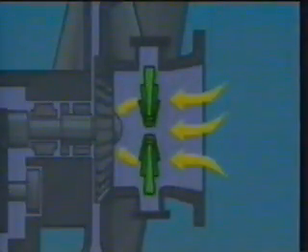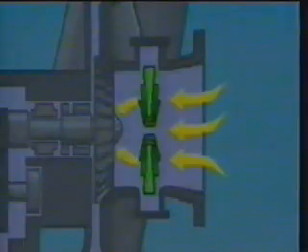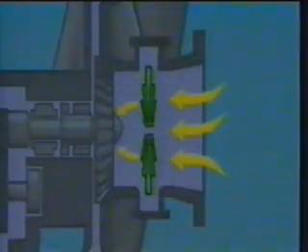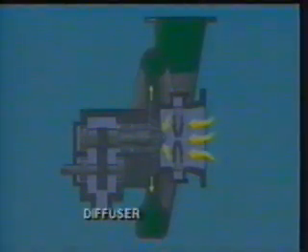Adjustable guide vanes are usually available on single-stage compressors and are sometimes used in the first stage of multi-stage compressors. These vanes can either be adjusted manually or automatically to control the angle of the gas flowing into the eye of the impeller to keep it running stable and efficient over a wider operating range. As the gas leaves the impeller, it's forced into a passageway in the casing called the diffuser. The diffuser forms an increasingly larger path for the gas to flow through.